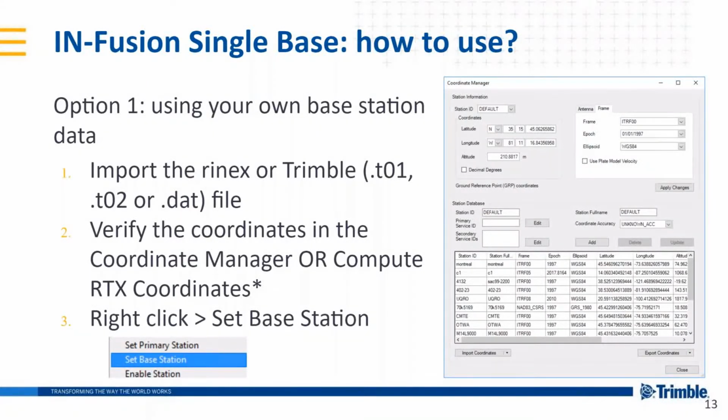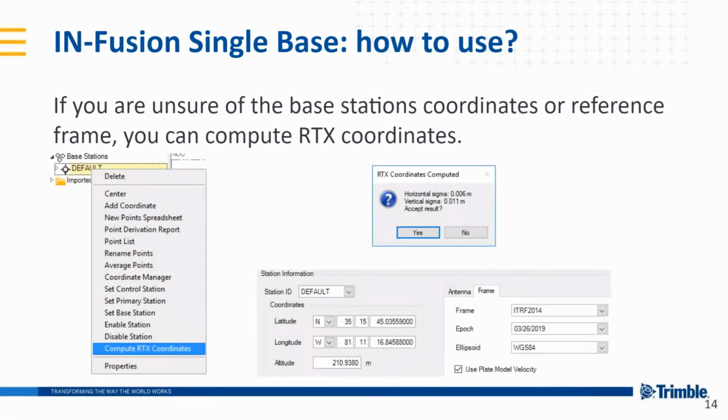And then we can set it as base station. So if you are unsure of the base station coordinates or reference frame, you can use these computed RTX coordinates.